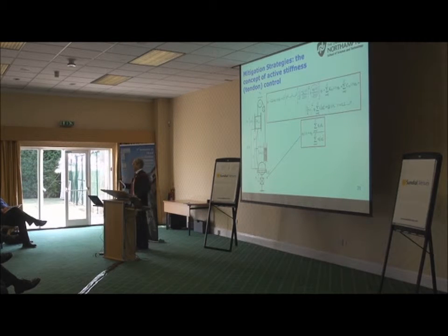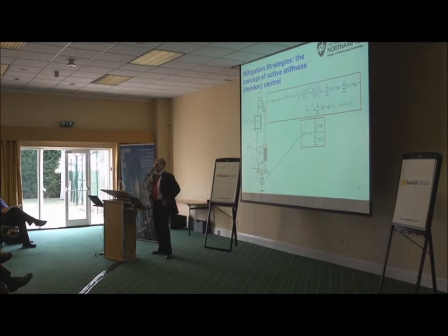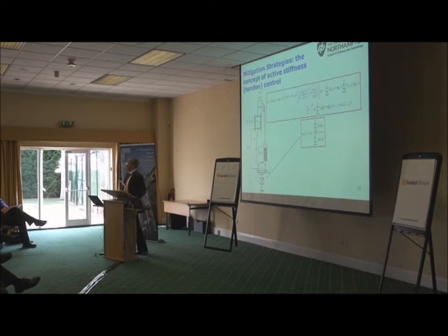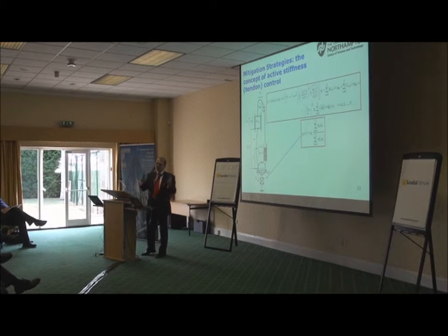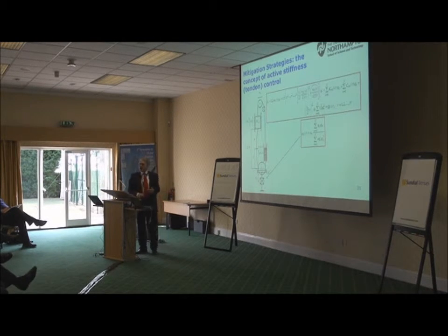Okay, so now, mitigating strategy, what will it be? Replace the ropes? No, it will not work. We have to apply something different. What we need to do is find how to damp vibrations using either passive or active methods. Passive methods means that you include a damping element into the system. However, ropes move, so hardly can you attach anything to them. We need to apply active damping, or an active vibration control strategy.